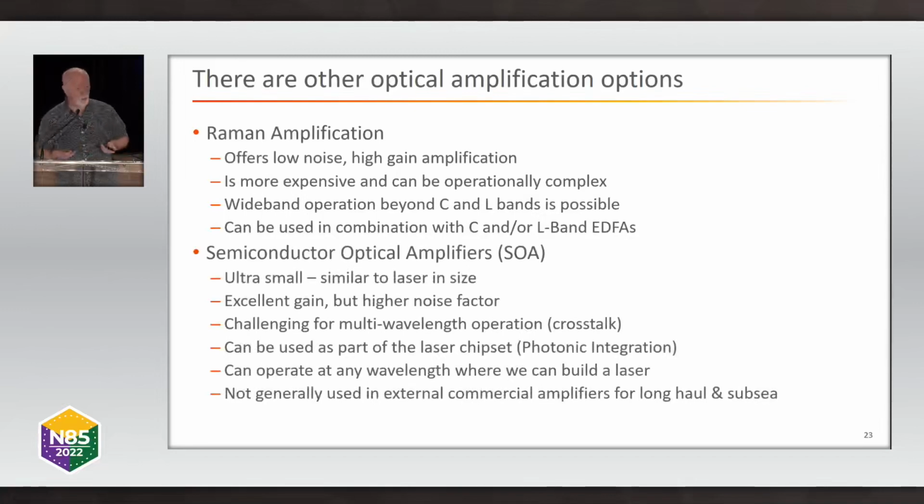There's a technology called SOAs, semiconductor optical amplifiers. They're very, very small. They're similar to a laser in size. They have excellent gain, but they have a higher noise factor than EDFAs. We tend to think of them as being very challenging for multi-wavelength operation. So like an EDFA will boost all of the wavelengths in the C-band at the same time. It's tricky to do that with SOAs.